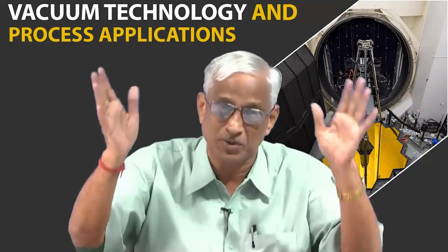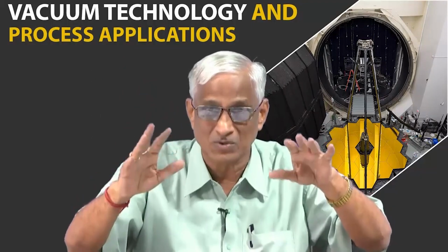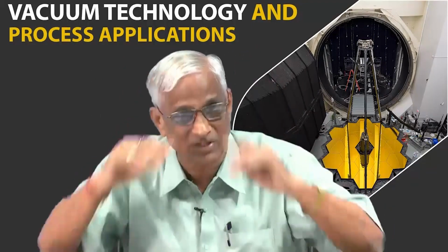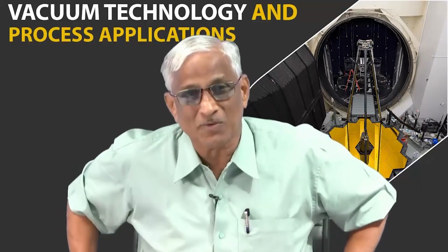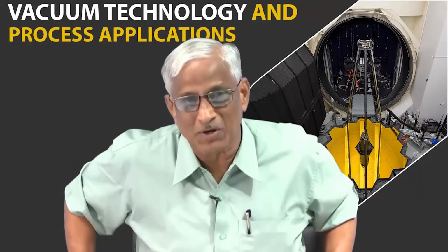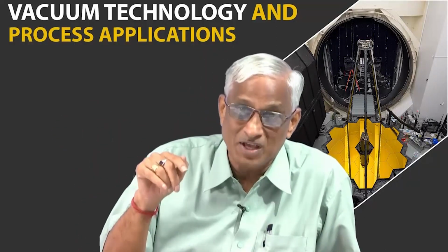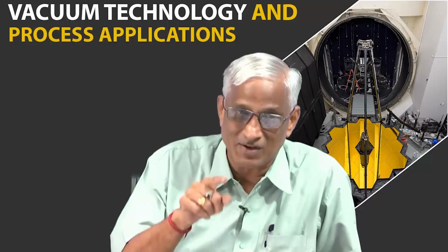Before that, the chamber should have been evacuated to 10^-2 torr, which is an acceptable vacuum for this high vacuum pump. All these things we have explained in the vacuum system of the diffusion pump or turbomolecular pump. That time we explained them as a part of pumps. Now, I am explaining it as a system. Again, these things will be explained when we go to the applications in a more careful and rigorous manner, because that will be a particular problem and particular solution for a particular application. Same terms will come there again.